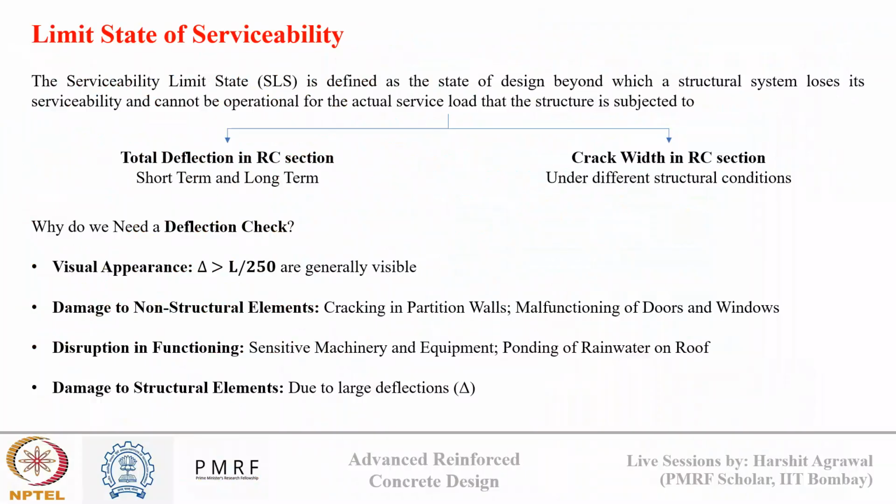So last week we started our discussion on the serviceability criteria of reinforced concrete design. We know the limit state design method is commonly practiced for reinforced concrete design, which has two parts: limit state of design and limit state of serviceability. If we just focus on design, we design for the worst possible loading conditions. But in reality, in actual loading conditions, we also don't want excessive serviceability issues in reinforced concrete. So this is where the serviceability limit state comes into the picture, which provides a limit on the reinforced concrete condition in service loading. Serviceability we can judge based on two criteria: deflection and cracking.